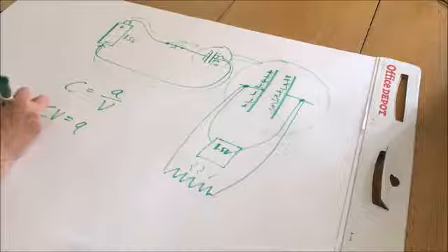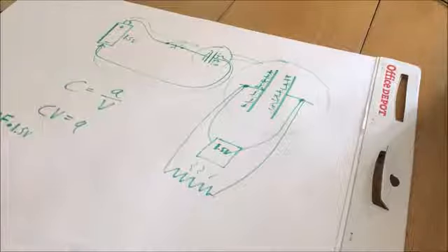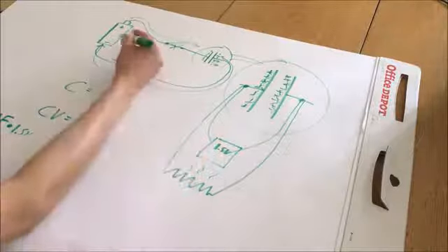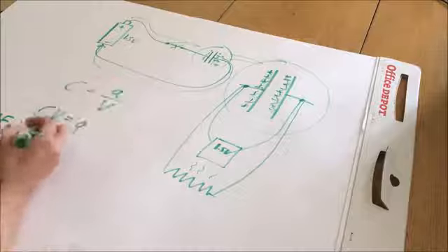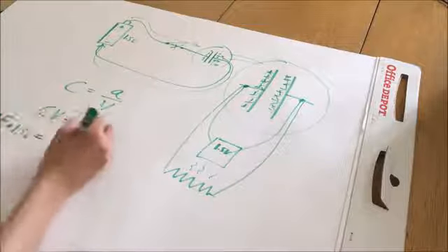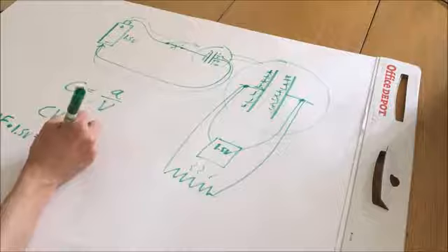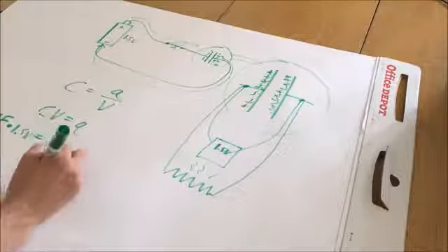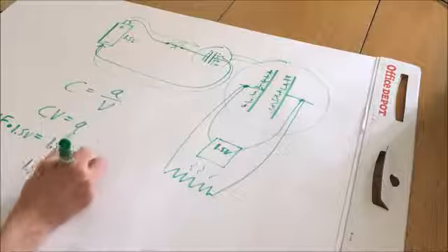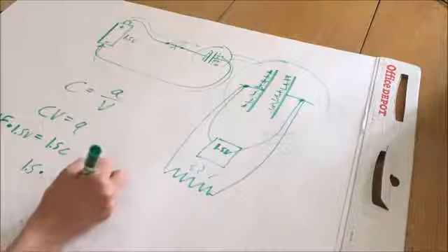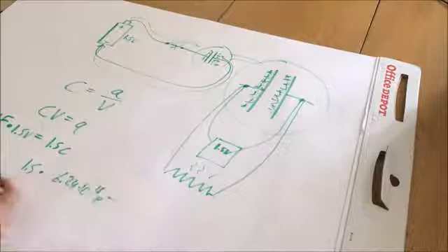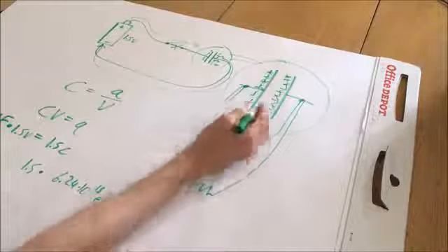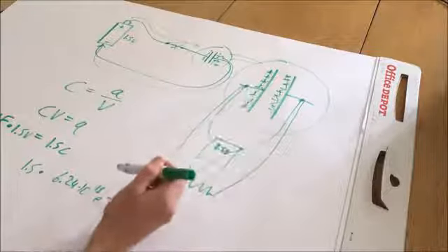But for the purpose of explanation, I'll say this is a 1 farad capacitor, and it's just been charged by this battery to 1.5 volts. Well, we can then calculate that Q is going to be 1.5 coulombs, or a charge of roughly 1.5 multiplied by the 6.24 times 10 to the 18 electrons. That's how many electrons we've pushed into this capacitor at 1.5 volts.